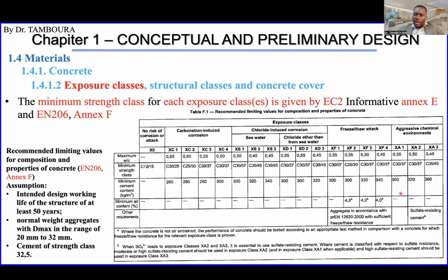And for the case of this kind of freeze and thaw attack, it means the XF, or for the protection against freeze and thaw, you have to add some air in your concrete, okay?